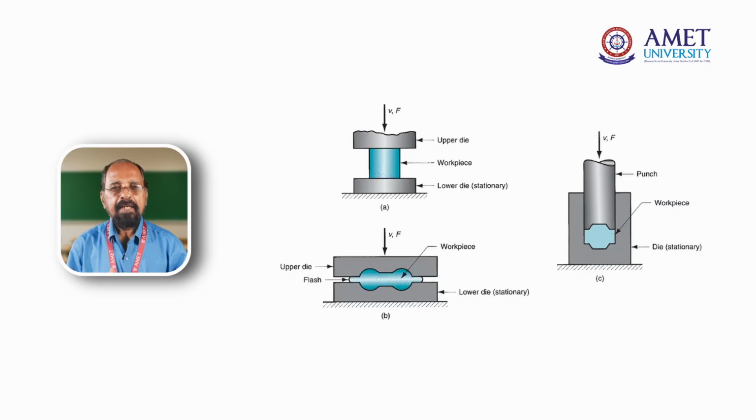Whereas in industries, there are 2 elements required. One is the bottom die, another one is the top die. Keep the material under hot conditions, apply a force, apply a load, but the load is going to be sudden. It is going to give you an impact load. The bottom die is going to be a profile and is compensated by the top profile. Both will give you the same product and subsequently it is taken up for processing. This is the hot forging process.